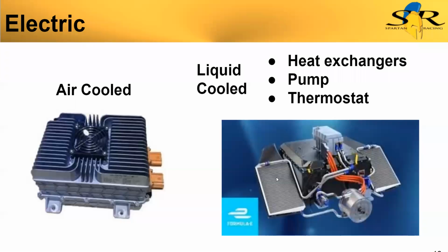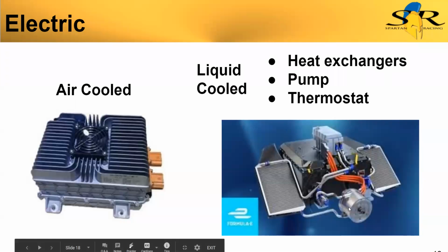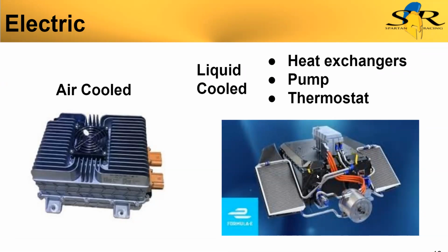And then I didn't really go through this picture on the side, but here's an electric vehicle situation. The radiators are side mounted. This is from a Formula E vehicle. The motor controller dumps a lot of heat and is mounted up here on top. This is the motor down in front. You can see all of this has plumbing going to it. And then the batteries as well are cooled, because they're offloading a lot of energy very quickly.